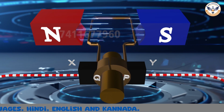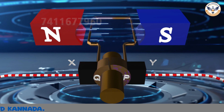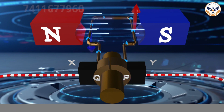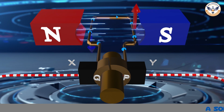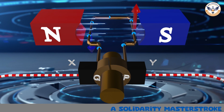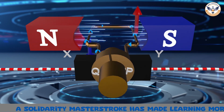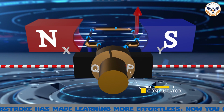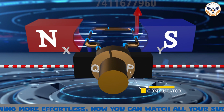At half rotation, Q makes contact with the brush X, and P makes contact with brush Y, resulting in the direction of current in the coil being reversed. Therefore, the current in the coil gets reversed and flows along the path DCBA. A device that reverses the direction of flow of current through a circuit is called a commutator. In electric motors, the split ring acts as a commutator.